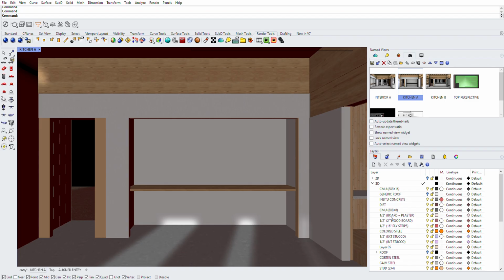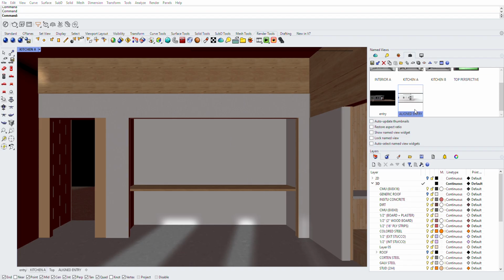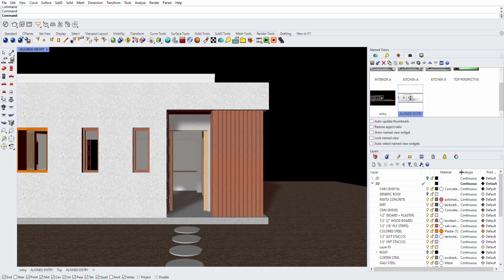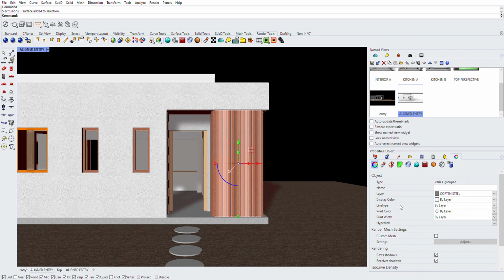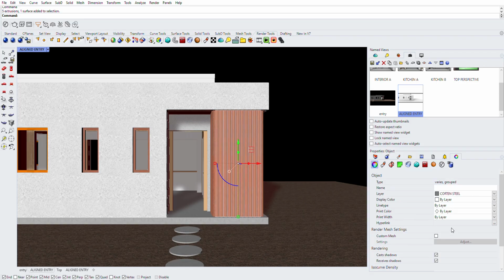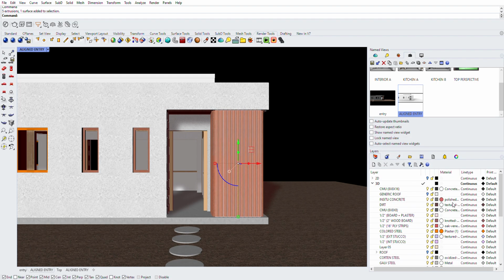And I think that's really helpful because, yes, you can set materials by layer, and then if I'm making changes, I basically will add a material here to the layer bar, and if I click on my objects and my properties are set up, I guess it's not. Well, regardless, I could go here and select all of my concrete. So all of my concrete layers selected, and then I can have the material apply to all of them.